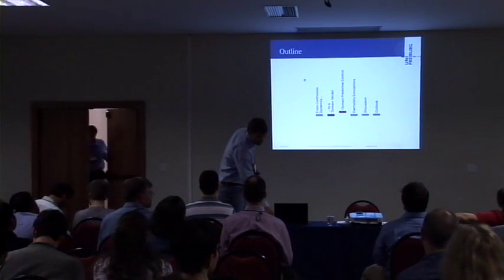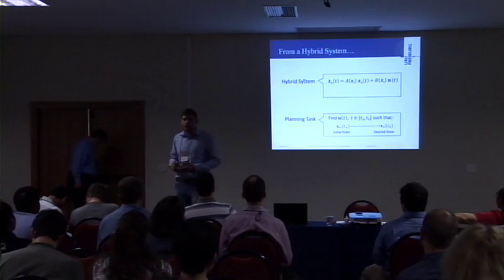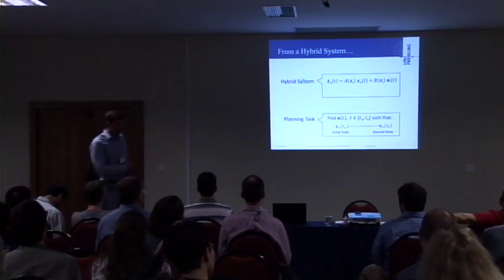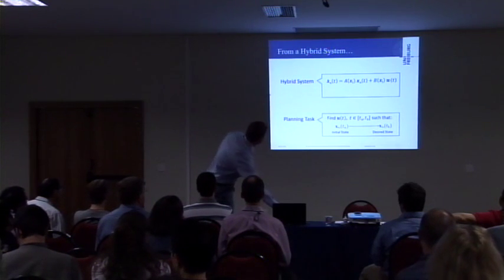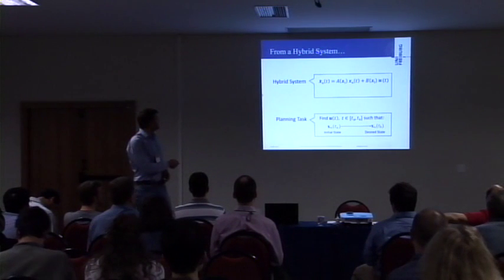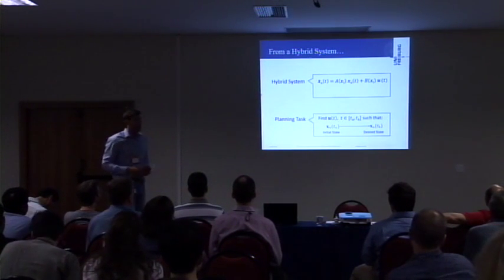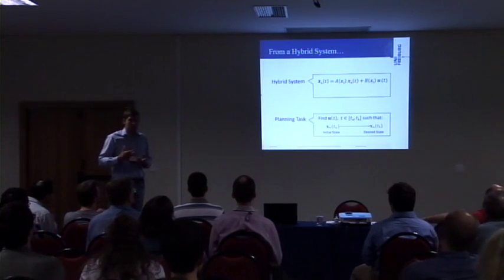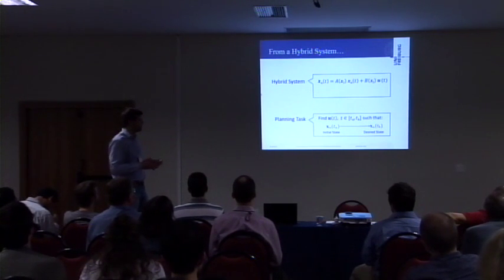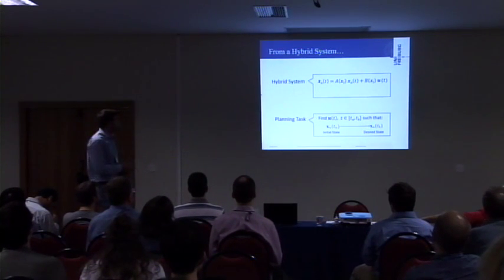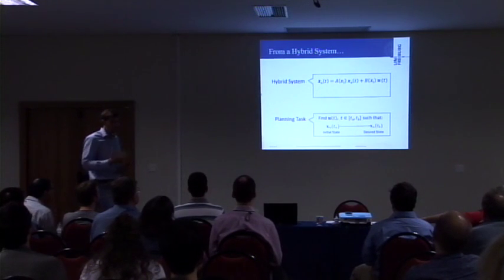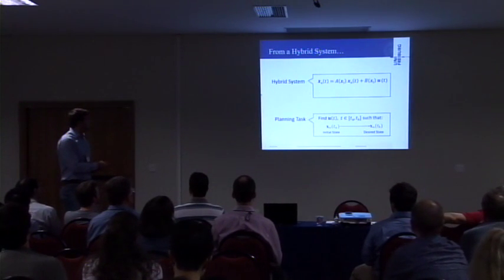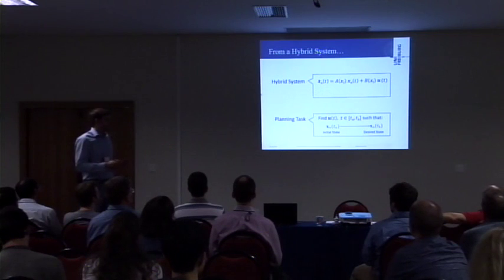So let's start in the beginning. What's a hybrid system? I think most of you are aware of that, but let's briefly go through the equation here. The hybrid system is basically a set of differential equations having a numerical state vector x_n, containing all the numerical information, for instance the current position or the current velocity of a car or the current angular rate of the satellite. And additionally, we have a logical state vector here defining the mode of the hybrid system. This could be, for instance, the current actuator configuration or the current system dynamics that we are using, underlying control feedback loops.